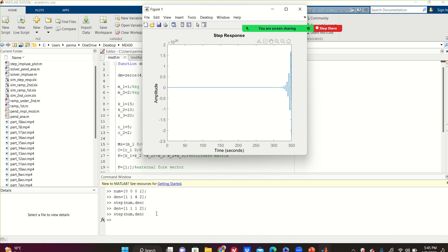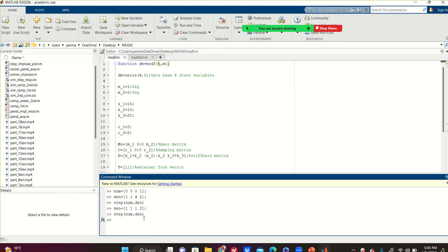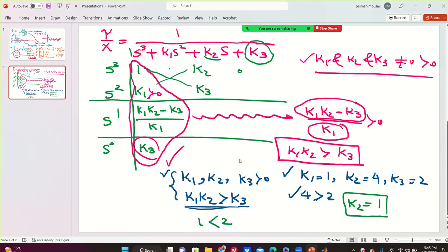So you see that based on rules of stability criteria, you can determine the domain of stability for the linear systems. So having that, if I say syms x, I want to find the poles of this system. Okay, I'm going to say solve x cubed plus x squared plus x plus 2. I expect to see right-hand side poles. As you see, we have right-hand side poles, a pair of complex right-hand side poles. So we did a Routh stability criteria. If you are not certain of the system parameters, it can give you where the system is stable and where the system is unstable. See what I'm saying? Yes?